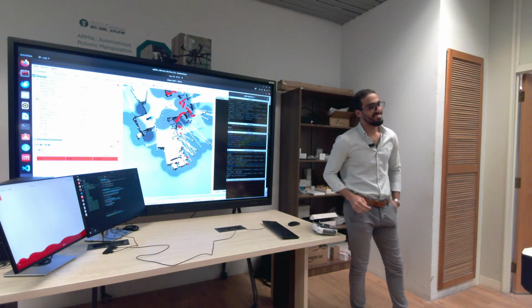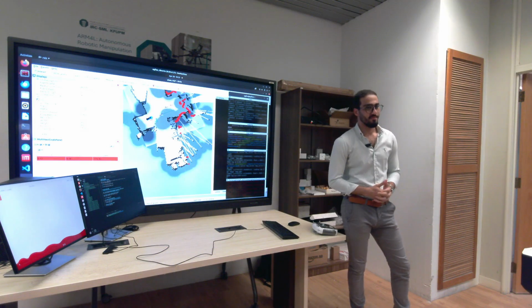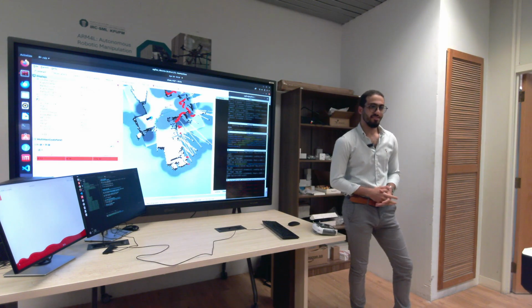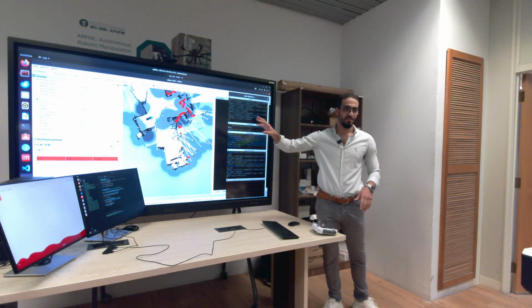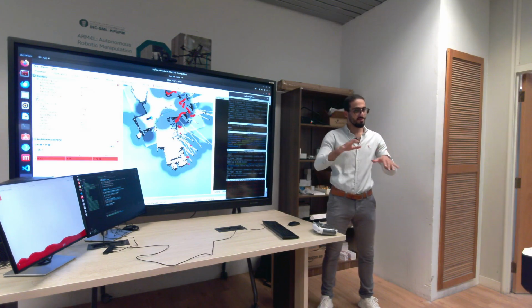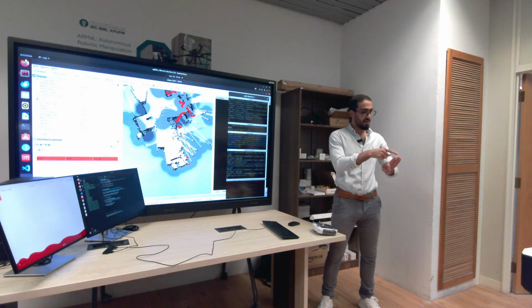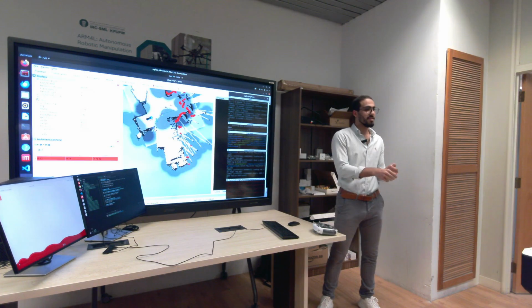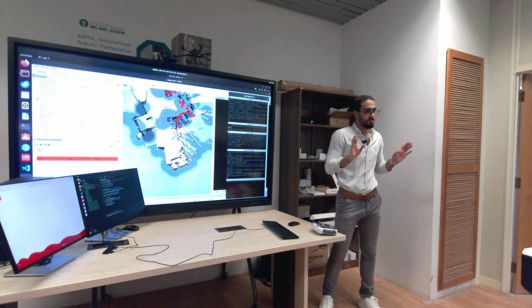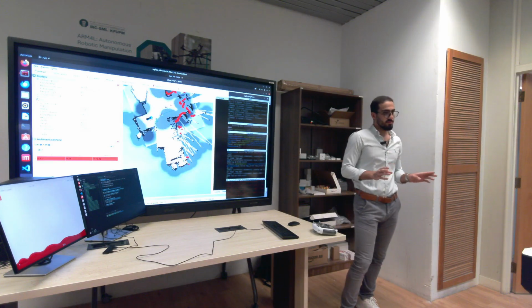It has a solution with the orientation of it. So how to not hit the wall? Maybe if it takes the straight path, it might hit the wall. Yeah, exactly. Actually, the answer is in the dark and bright areas. In the beginning we already discretized the map into three things: black, white, and gray. The black is obstacle, the white is free cells, and the gray is unexplored cells, unknown to the robot.